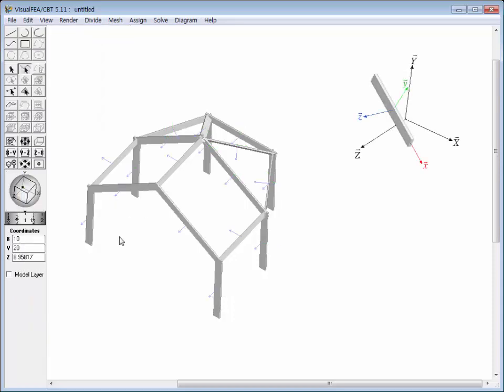The orientation of a member section is represented by the local coordinates of the member. The axial direction is always defined as the local X direction. The width and height of the section are measured in the local Y and Z directions, respectively. The local coordinates are initially determined for each member by the axial direction and the global coordinates. The local Y and Z directions are obtained using the equations of vector product shown on the screen.